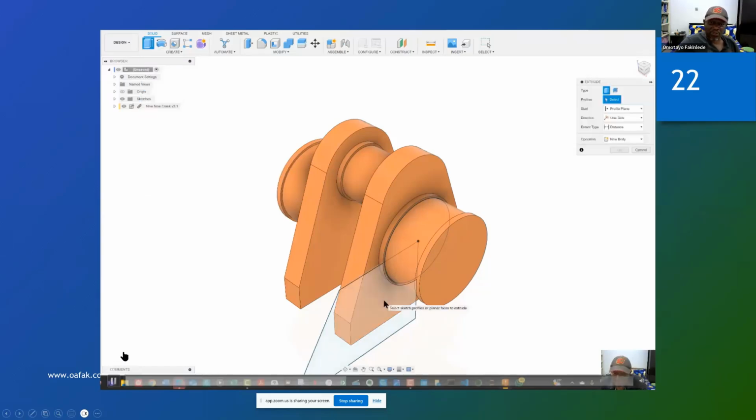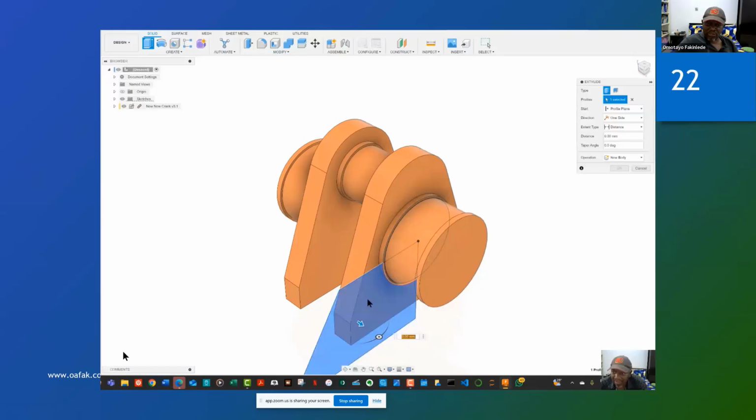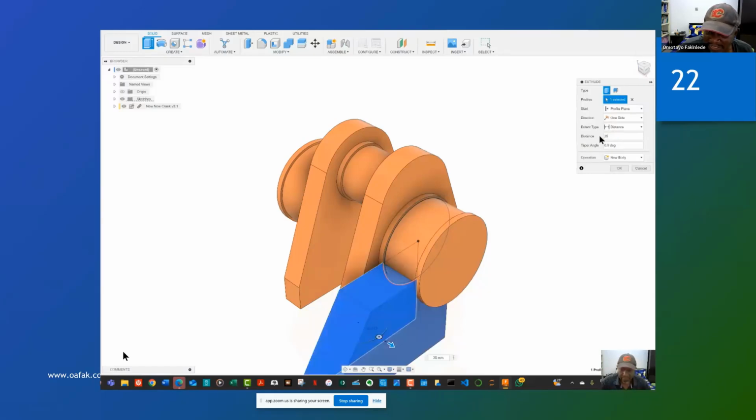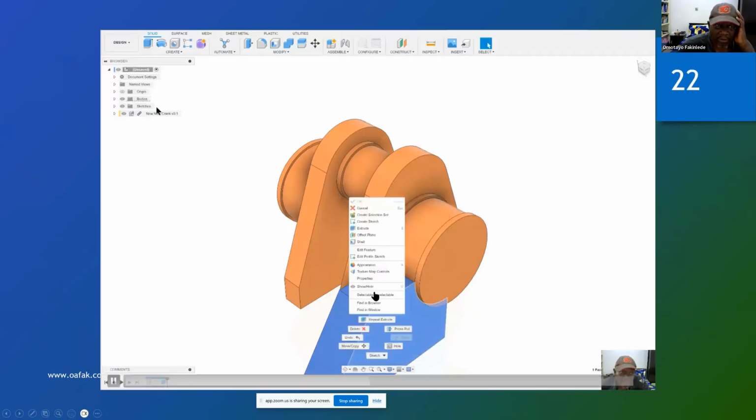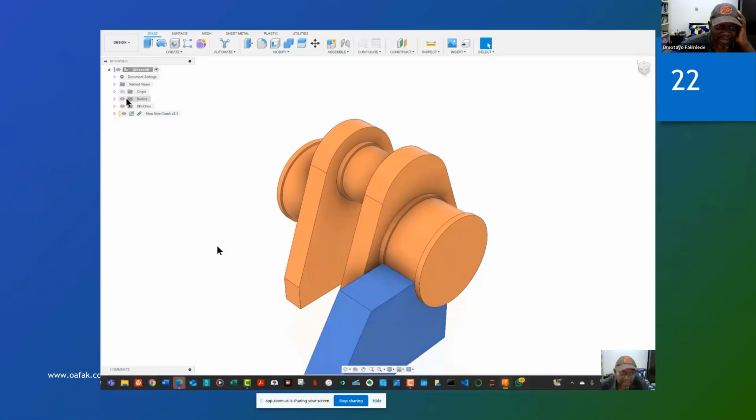We now want to extrude, and then we click that. We choose that as the extrusion profile, and then we choose the distance to be 35 millimeters. You can see it just simply fills the groove that is there. It just fills the place provided between those two grooves. Okay, so when we are happy with that, what do we do with that?